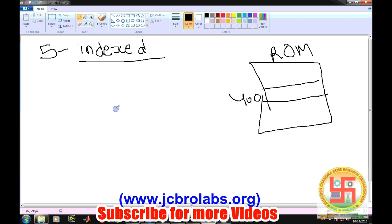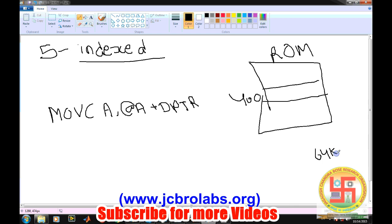There are famously two commands which are used for indexed addressing mode. One is MOVC A, @A+DPTR. If you remember, we learned that DPTR is the data pointer register, and it's a 16-bit register. So our external or internal memory can go up to 64 kilobytes. That is why this DPTR has to be a 16-bit register, because it has to access 64 kilobytes of memory.